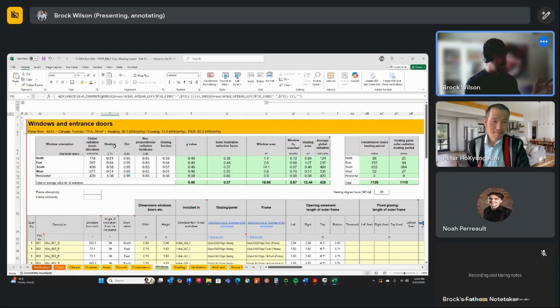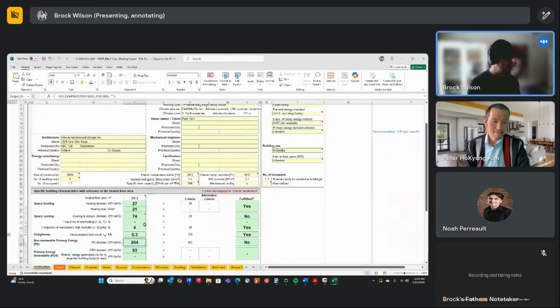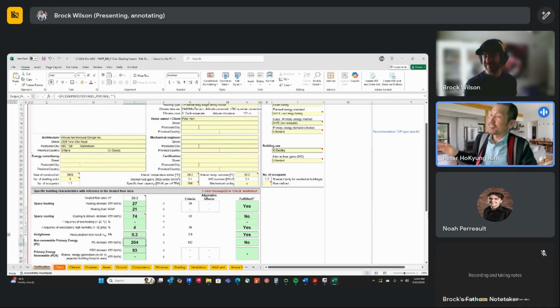Yeah. So with that, turning them all on right now, we're still hitting the heating demand, which is good, but we're just not hitting the cooling demand. So that could be adjusted, like you had said. There's some potential for operational shades, and or whether or not the different coatings are being used. So that's something that we can further investigate to see if we can get that cooling load down and keep your windows.